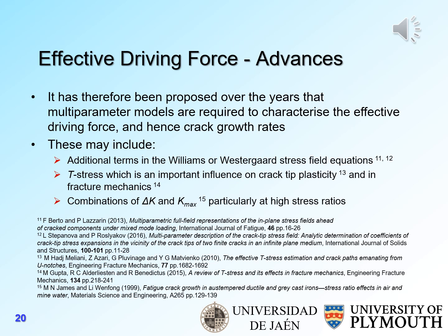The T-stress, which is known to be an important influence on crack tip plasticity and in fracture mechanics, and perhaps on combinations of delta K and Kmax, particularly at high stress ratios. And I give you there a reference by me, but I must say that my memory is that Suresh and Ritchie proposed this first, but I can't find the original reference for that.